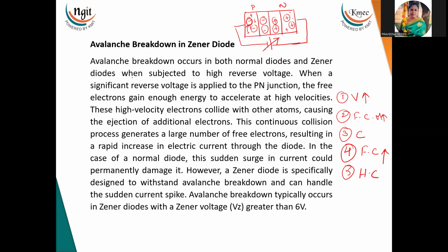So this is about the breakdown region. Because of the external supply, the charge carriers attain high mobility and collision takes place. Collision means these charge carriers hit the atom, thereby generating more free charge carriers, in a continuous form, and this leads to very high current. In the PN junction diode also, I have explained the breakdown.